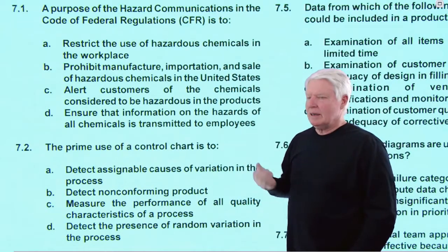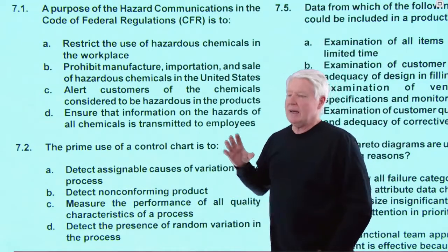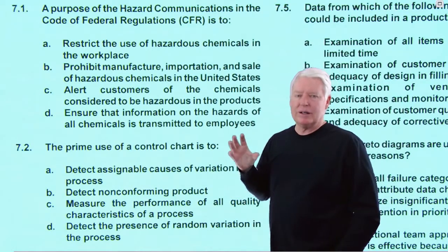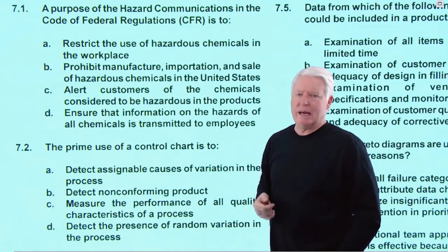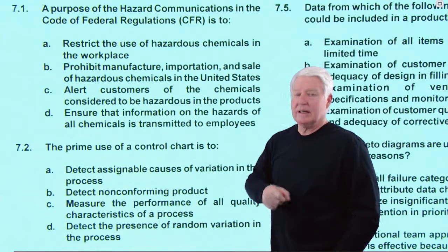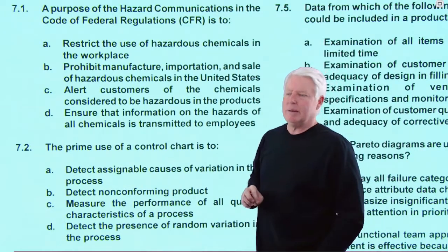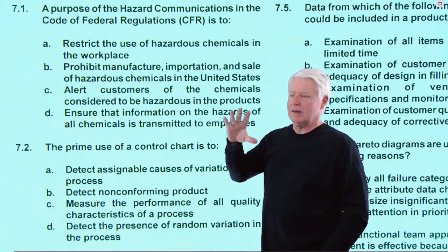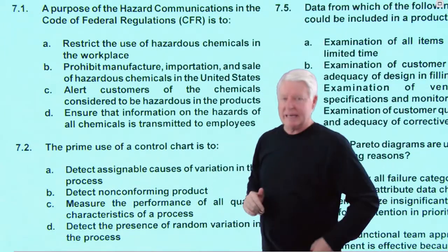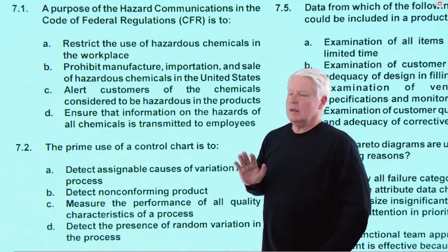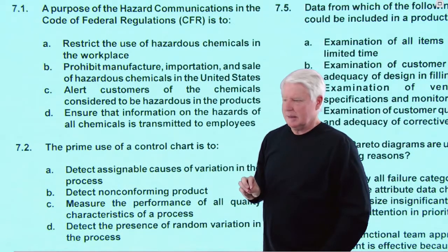No. You don't even know where the spec limits are necessarily when you're plotting on an SPC chart. And besides, in SPC you plot averages, not single events. And when you compare averages to the spec limits, that's a worthless comparison. You need to remember that. You don't try to determine capability with SPC because SPC uses averages, and per the central limit theorem, that squeezes everything down. So, in short, don't compare control limits to spec limits.